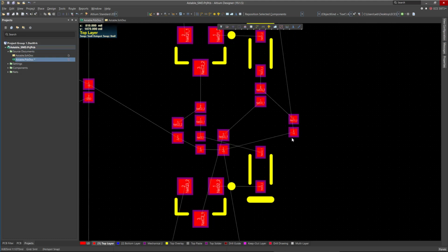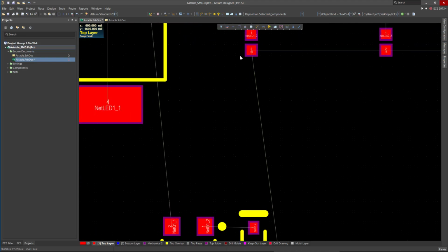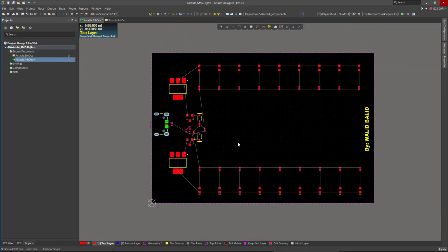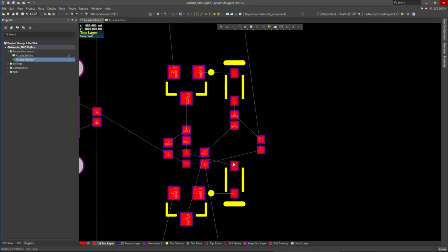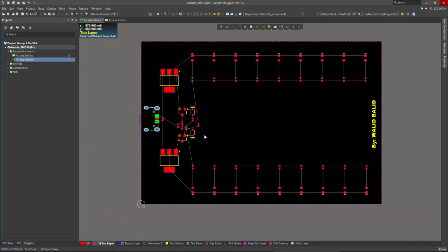You might need to change the component position after you place them, during the routing process. So this is also very common. You start with initial positioning, you start with planning as we talked about in previous sessions, and then you start placing your components, and after that, if you find a better placement for the traces to better fit, you change or move the components.